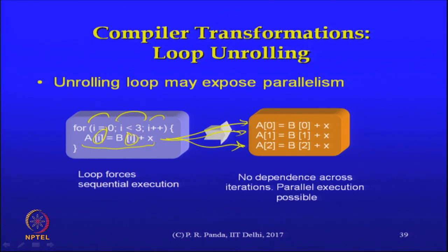When you construct the DFG for this entire basic block now consisting of the 3 bodies, there is no conditional among them. So, you have the whole thing being represented as a single DFG. There you will find that these are actually different data elements, and there is no obvious link between the 3 iterations. So, as long as you have the right resources, you could actually schedule all of them in parallel.